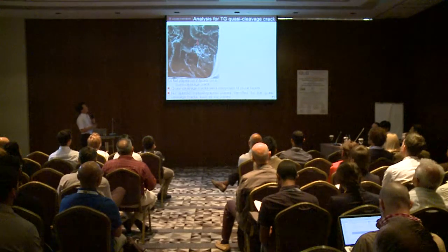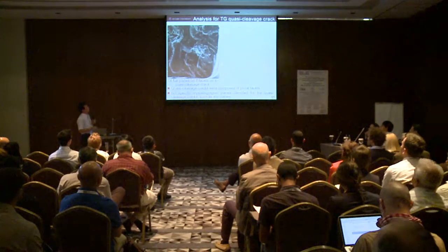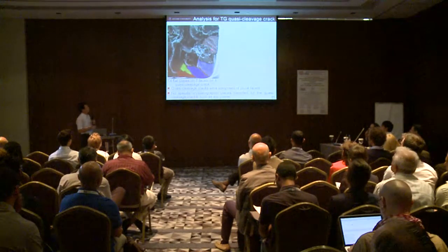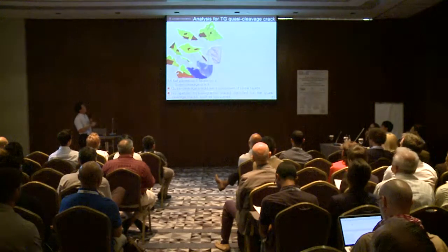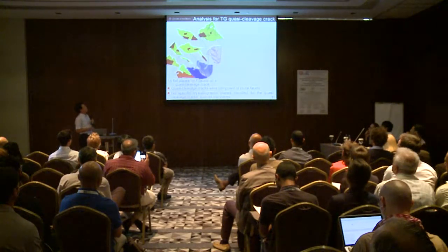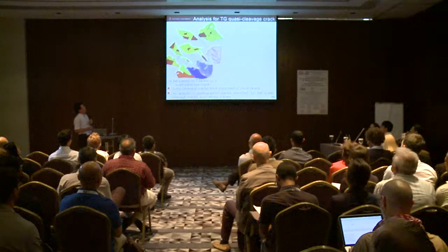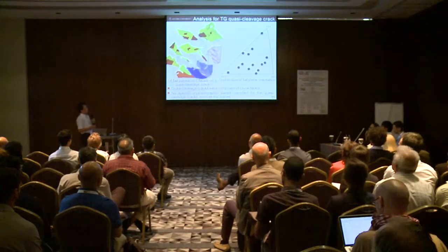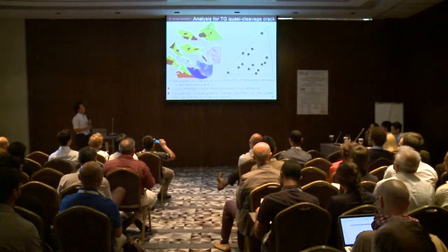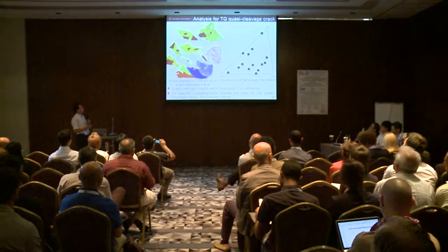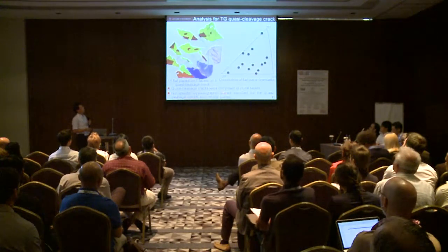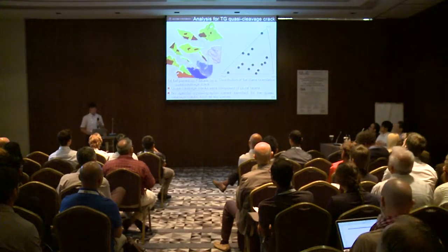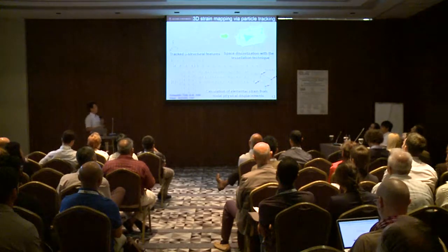And this is transgranular crack. We are looking at an SEM micrograph, and we can see a quasi-cleavage crack here. And then we can find 7 facets on this quasi-cleavage crack. And if you look carefully, we can find 14 very flat planes on the 7 facets of the quasi-cleavage crack. We measured the crystallographic orientations of these flat planes and plotted them onto the inverse pole figure here. And the data points are widely distributed, and we couldn't find any association with crystallographic planes such as slip planes and cleavage planes or something like that. So it is fairly non-crystallographic. So we would like to further analyze the transgranular fracture behavior.